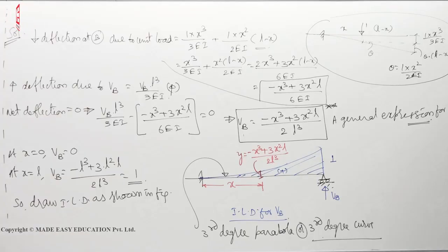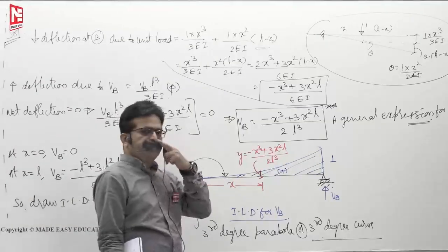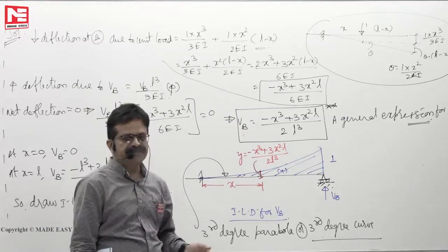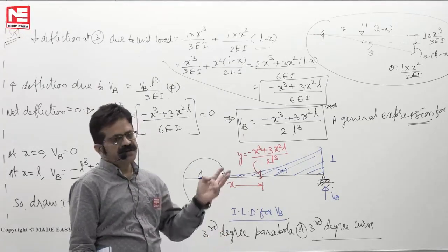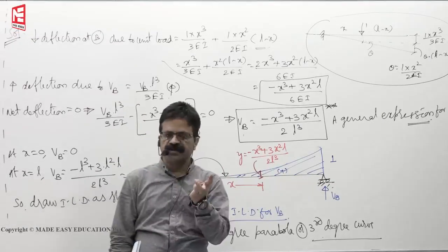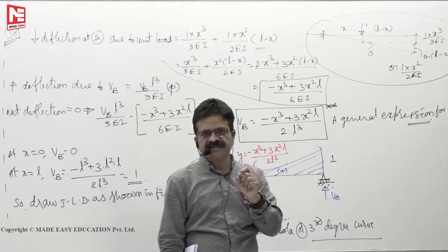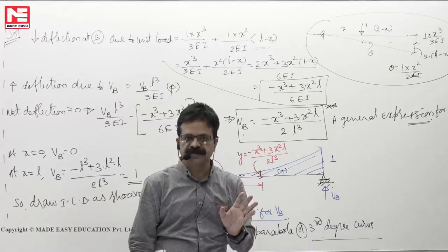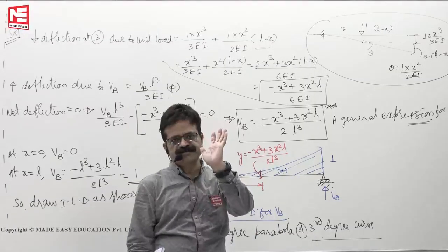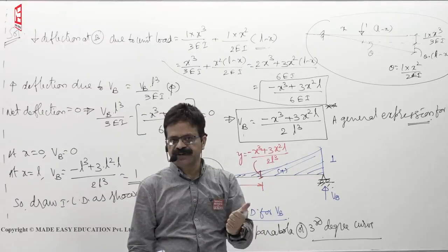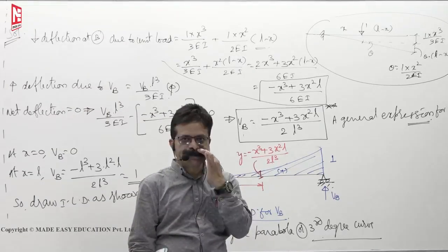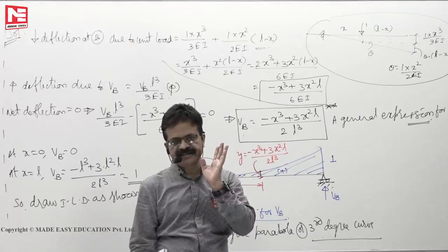Now, your observations are like this. If we have a statically determinate structure, removing the support, cutting the beam or assuming an imaginary hinge will make the structure unstable. Then when you give displacement, it undergoes rigid body rotation or translation, so you get all straight lines.